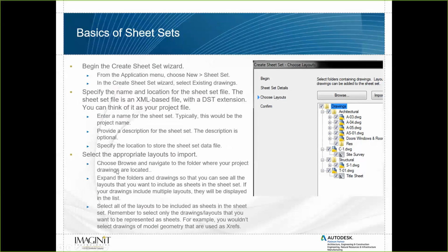Then you select your appropriate layouts, and you'll be able to see all the drawings. I'll actually go through the example and walk you through this so that you can see how we do this. For example, you wouldn't want to select the drawings of model geometry that are used in XREFs. You only want the pages that you want to include in here.